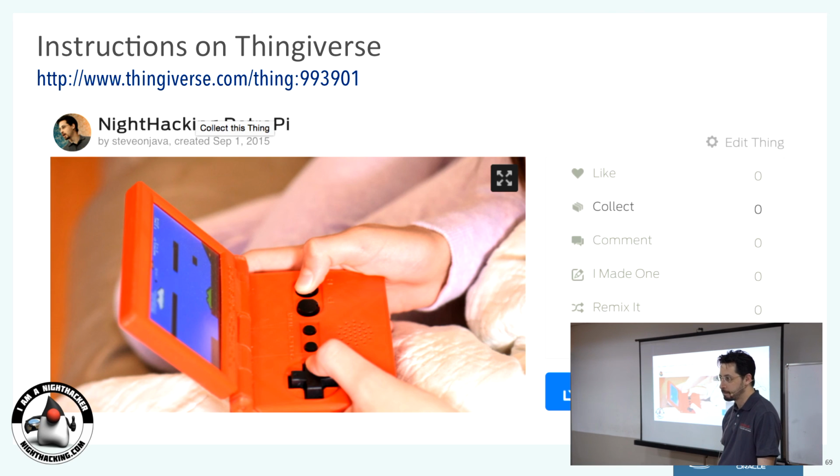Okay. So the program will capture all your buttons, right? Or the button movements and all. So I modified the HalfNes code base to support GPIO. So it's using a library called Pi4J for the GPIO support, and it's capturing all of the inputs. Okay. And then it's treating that as a controller. Okay. And also, I have support for USB controllers too. You can hook up an external USB controller and then play with a standard gamepad.